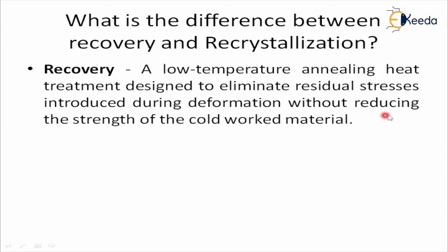The main salient feature of recovery is that it is not supposed to reduce the strength of the cold worked material when it is happening on the material. So that means during recovery, there is no reduction of strength of the material. So this is the main feature of recovery.